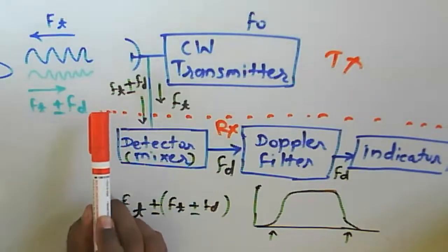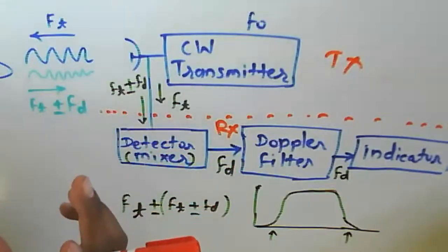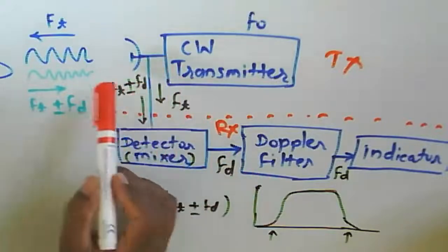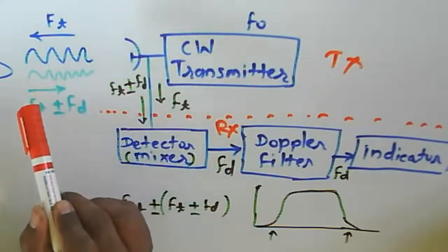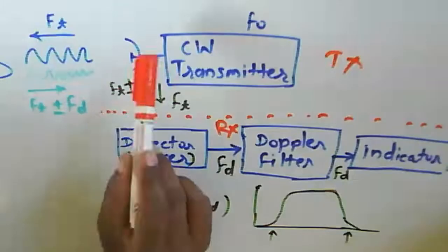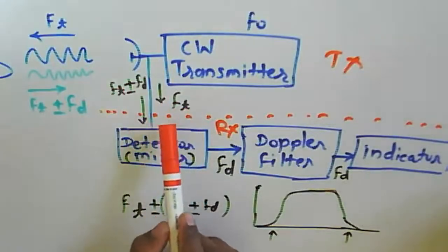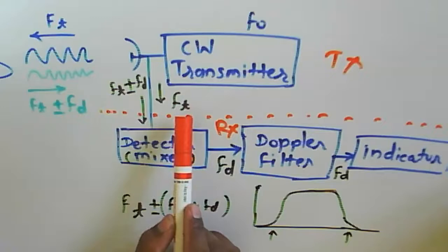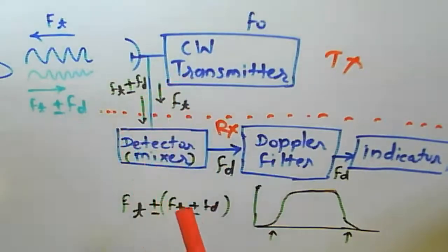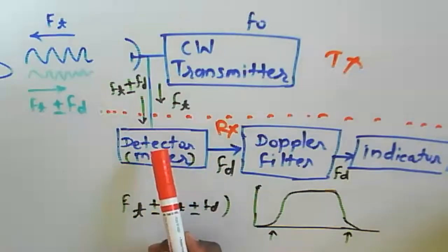as well as we are getting some clutter signal. That clutter is nothing but a signal received from the nearby target or environmental objects. When the transmitted signal reaches that environmental object, it will scatter the signal, and that particular portion will reach the receiver. So again, we need to define what the clutter is. We need to remove that clutter, which is to be considered as noise. So we are supposed to remove that noise at the receiver.